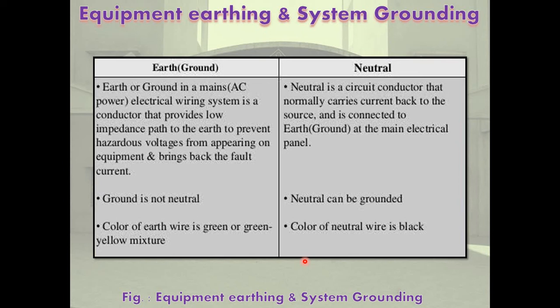Neutral earthing at each voltage level: the neutral of the star connected three-phase winding of a transformer can be earthed. The generator neutral can be earthed. If the neutral point is not available, a separate star delta transformer is arranged so that the star point can be earthed. Sometimes a special earthing transformer having zigzag winding and a neutral point is provided. The rule to be followed is to provide neutral earthing at every voltage level.